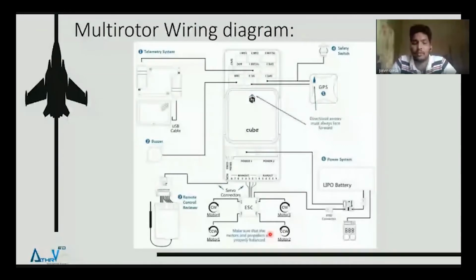That is, it will be a clockwise propeller or a counterclockwise propeller. And this is very much essential because a counterclockwise propeller will not generate the same thrust if it's rotated clockwise, and there will be a lot of vibrations if you put the wrong propellers on the motors. Then usually a flight controller is powered by a 5-volt source.